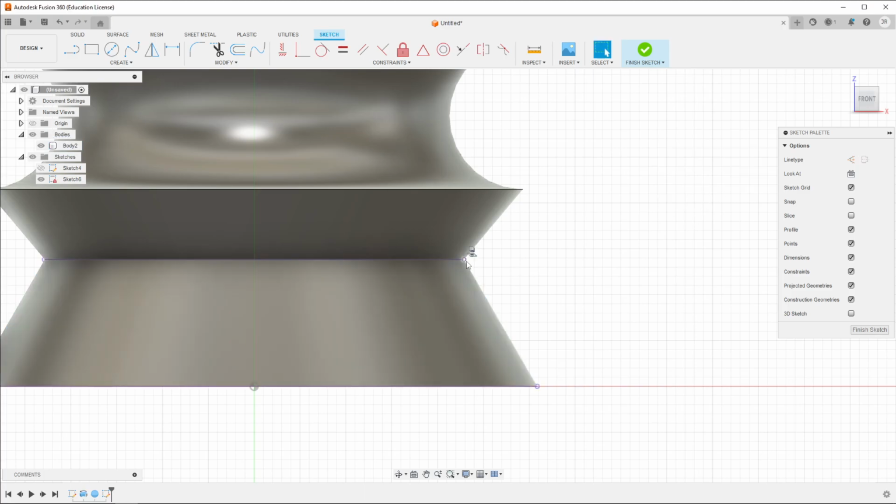Click OK. Notice it gives us these 2 points. It gives us these lines because they're obvious, but this line is not along. But I can very easily make a construction line. Hitting L for the line tool, I'm going to use the line construction option, and then just make a line between these 2 points, and there it is along that edge, which is exactly what I want.